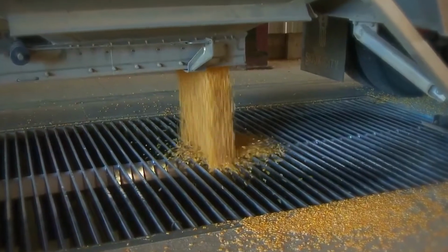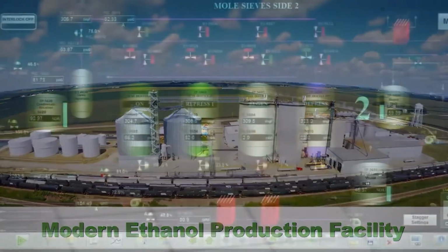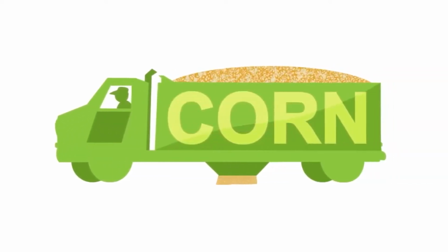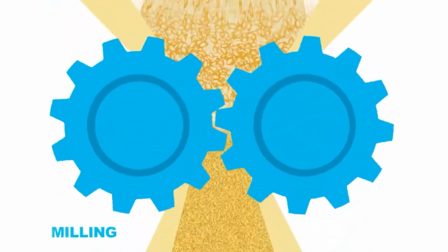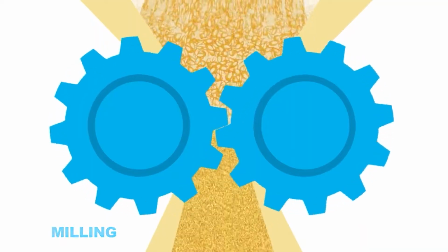So, how do you get ethanol from corn? It's a simple biological process which utilizes some very sophisticated techniques and equipment. It starts when shelled corn arrives at the facility and is quality checked. The corn is then ground to a fine granular consistency so that the starch matter in the kernel is exposed. The dry cornmeal is mixed with water to form a slurry mixture called mash.